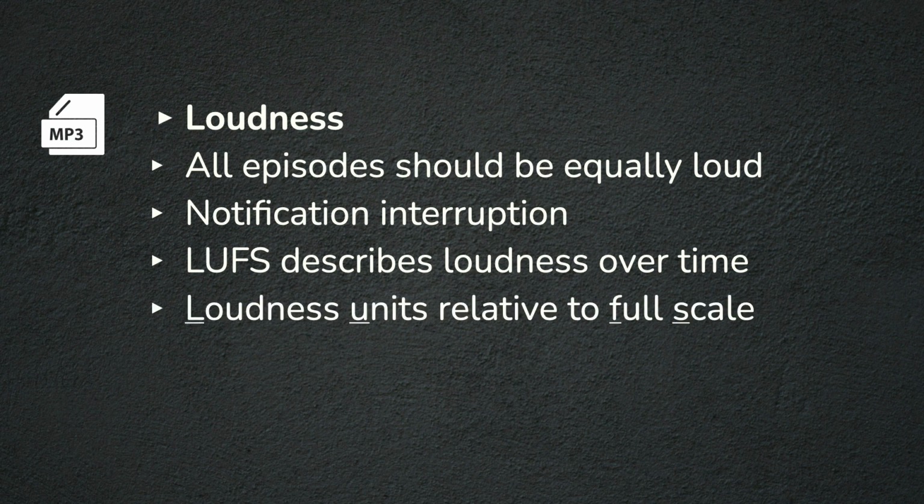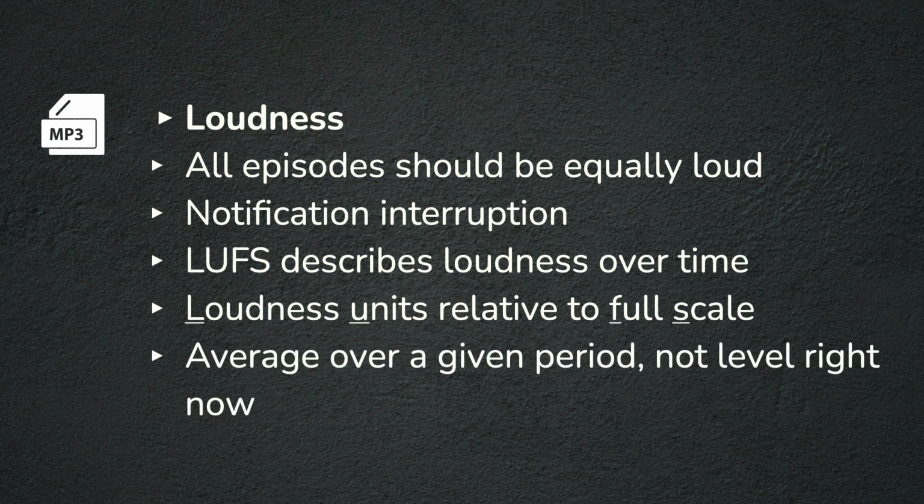which describes the loudness over time. It's a perceptive measurement, and it stands for loudness units relative to full scale. And it's an average over a given period, not sort of right now. So if we think about a decibel measurement, that's a signal measurement. That's saying how much electrical signal is going through right at this millisecond, whereas loudness is a perception over time, and it's much more human.